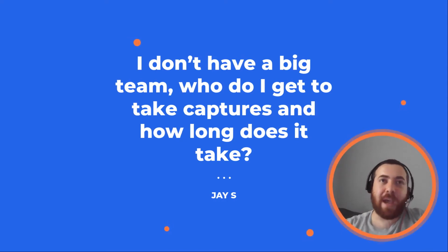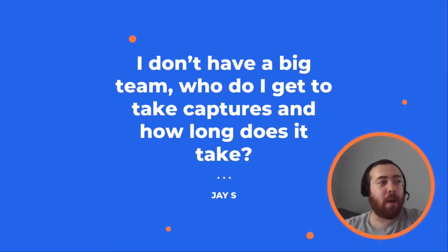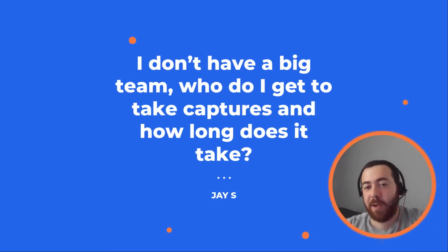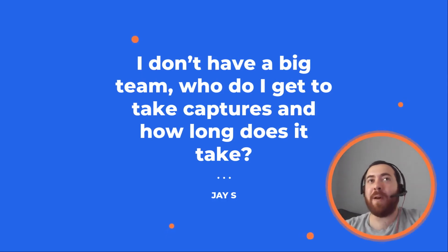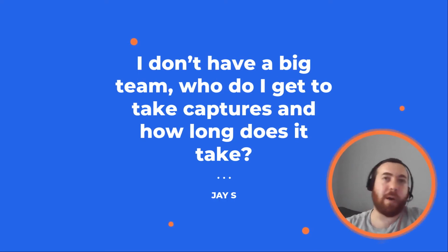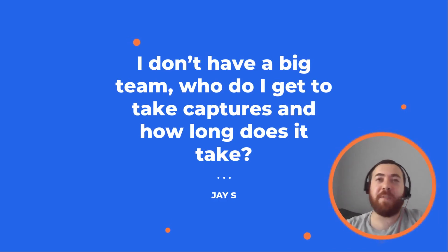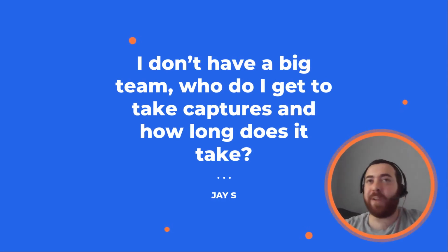One of the most common ways is through a 360 camera and a 360 video. And what we like to say is you can cover about 1,000 square feet in a minute with a 360 video capture. So a large site can take 20 to 30 minutes or so to capture. And then if you capture in the morning, depending on the size of the capture you take, it'll be ready in anywhere from 45, 50 minutes to a few hours.